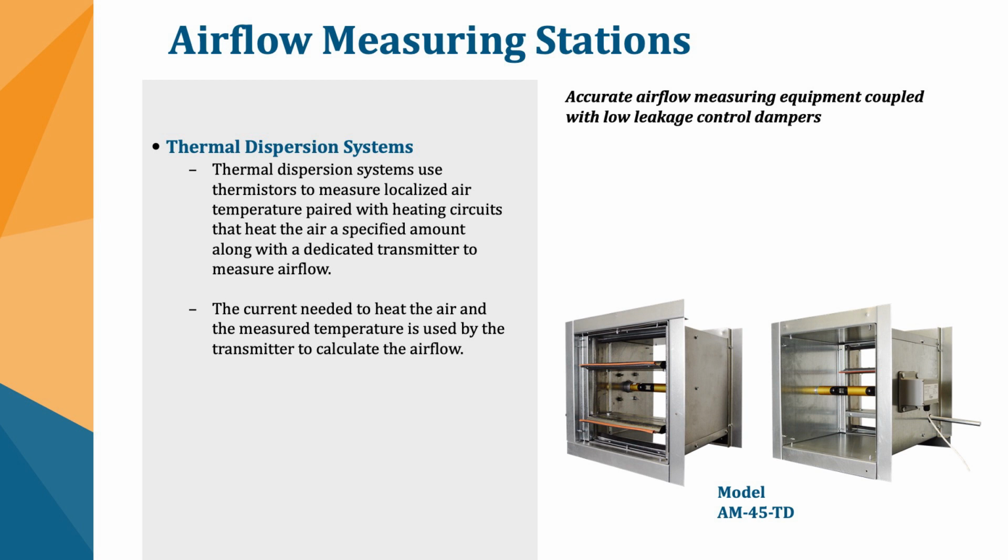Now, one question I've actually gotten, which kind of makes sense when you're dealing with things from a traditional volume control damper standpoint, is most volume control is done with opposed blade dampers. You can typically get a more accurate control of the volume with that. The problem that we've seen with testing some of these in-house is although the opposed blade dampers do control the air volume a little bit better, they also create more non-laminar flow when you're adjusting that.